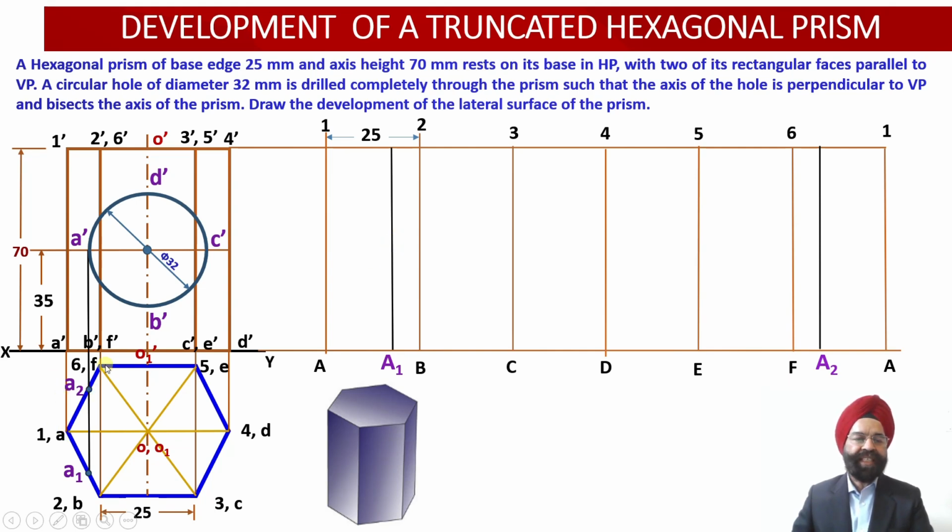Similarly, onto the rear side we can check as we move along the rear side. So from the point F, as we move towards the point A alongside the edge FA over here, at a shorter distance from point F or at a longer distance from the point A, either one of these 2 distances we can measure, point A2 will be located between the edge points F and A over here.